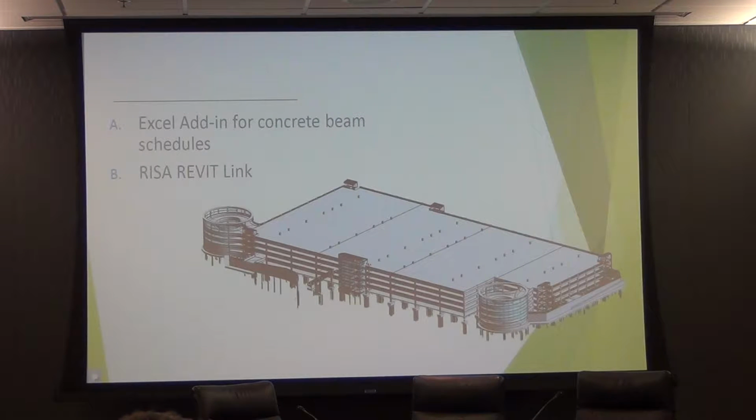And so consequently, we created a hybrid process, and I think this is something that everybody will probably have to do to some extent. You create a hybrid process whereby you say, well, we like what this does, how can we get this data from RISA to something else, and then get that something else into Revit, and once again, minimize the data handling. So what we did is